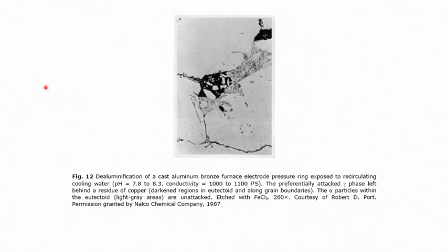So, these two kinds of corrosion are very important types of corrosion. In this talk we discussed two important corrosion processes: one is intergranular corrosion and another one is selective leaching. Both corrosions are observed in alloy systems, not really pure metals. In one case, the corrosion propagates through adjacent grain boundary regions, and for this intergranular corrosion,